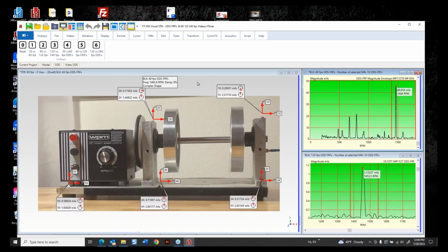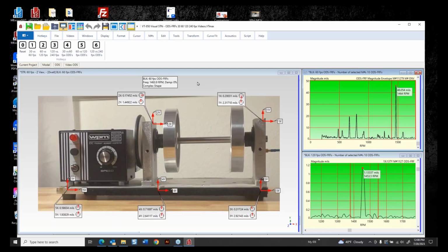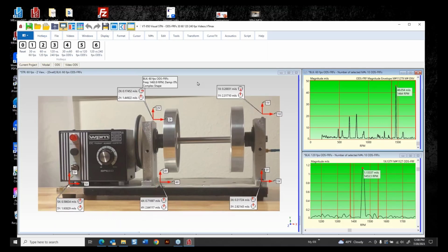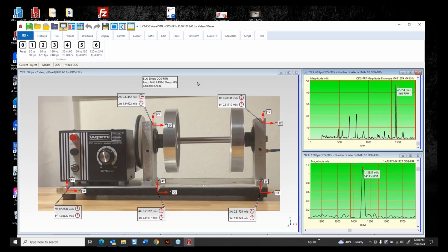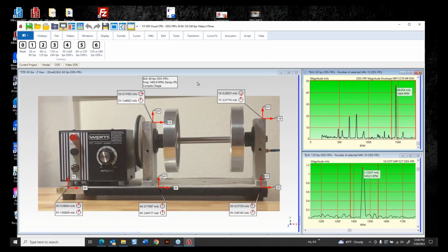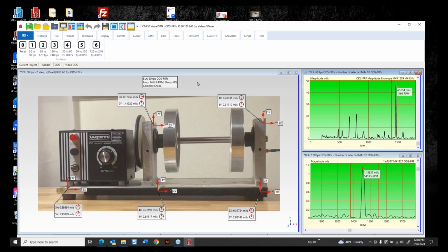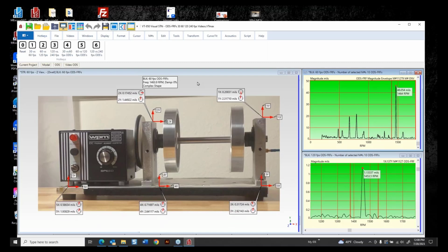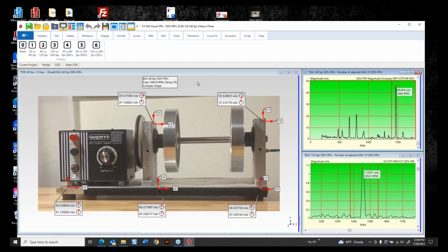There's a little edit feature in the cell phone for the slow-mo feature, because the slow-mo does record at 2 different speeds, and you need to remove that either in the cell phone or in MEscope with the video wizard. Just don't use the beginning frames and the ending frames of your video, and then you'll be fine.